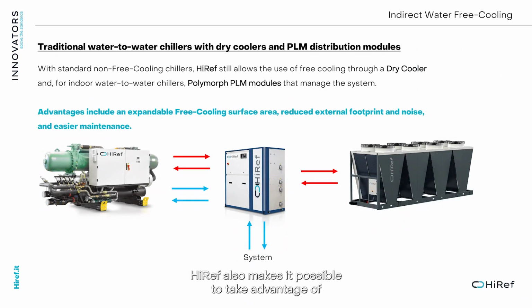HiRef also makes it possible to take advantage of indirect water-based free cooling with a solution featuring water-to-water chillers combined with the PLM module. In this way, with the PLM module, we are able to use, as in the previous cases, 3 operating modes. Mechanical operation, where cooling is provided by the compressor and the heat dissipation is handled by the dry cooler.